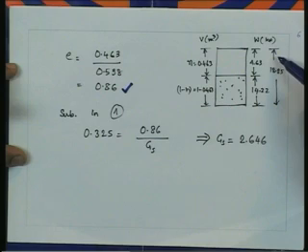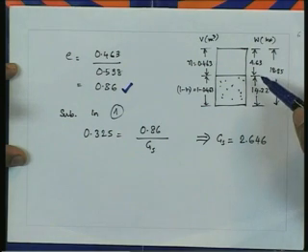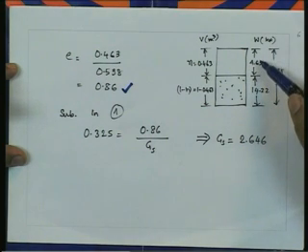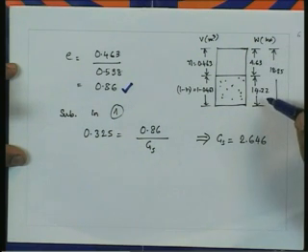The saturated weight was given as 18.85 kilonewton per meter cube of soil. That means the weight of water is equal to 4.63 kilonewtons from the water content, so the weight of solids is equal to 14.22 kilonewton, that is what we have deduced previously.